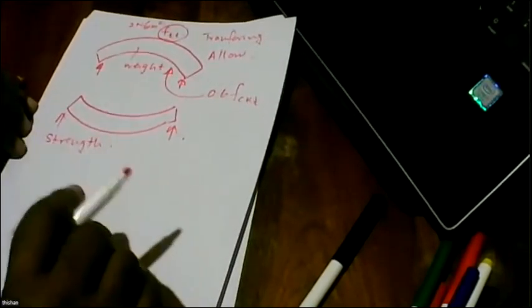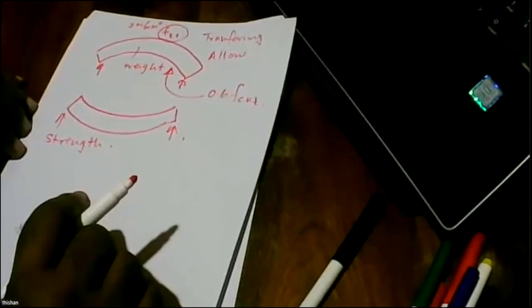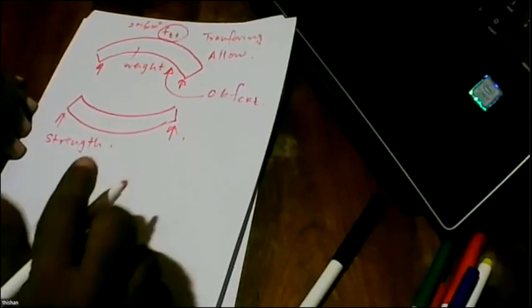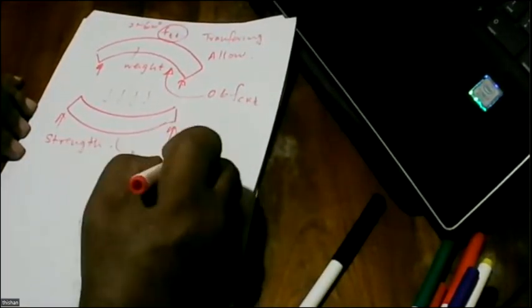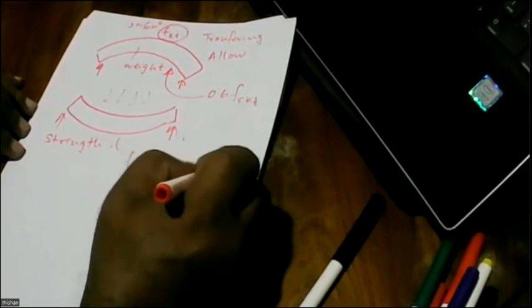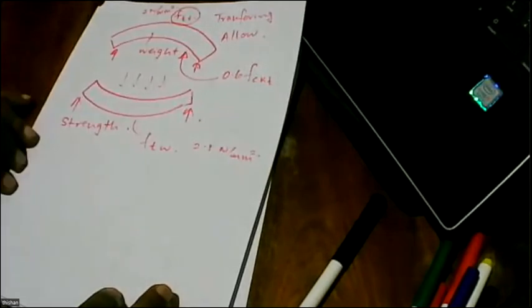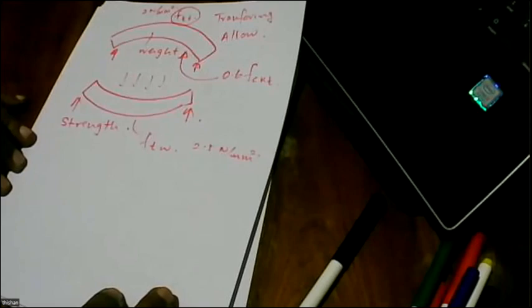Now, when it fails, it does not fail due to permanent loads. It fails due to the maximum load when we apply whatever the loads. So here we can have another tension at working load, which may be about 2.5 newtons per millimeter squared. But if you want, you can go for higher values. But then you have to deal with the cracks, because beyond this, it's going to crack.